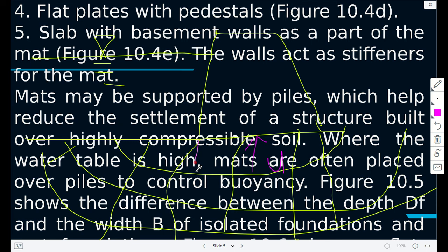We just find the water head here, maybe it's 10. Then you find the water head there, because as water flows here, it loses head. You can plot it. If you did flow nets, you can remember this. And then you find the head there. Of course, the head is reducing because as it goes, it loses head. And then you draw some shape. Normally it is a regular shape, could be a trapezium, could be a rectangle.